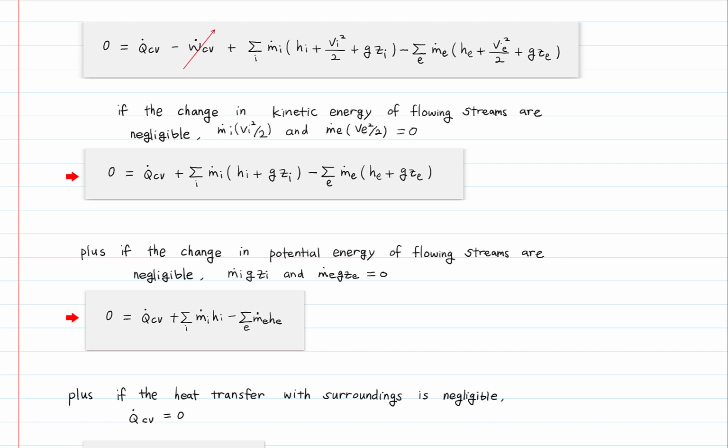We can simplify the general form of the energy balance equation with appropriate assumptions. Heat exchangers do not involve any kind of work other than the flow work of the flowing streams. The change in kinetic energy is small, so it drops out. The difference in elevation between the inlets and outlets is small, so potential energy drops out.